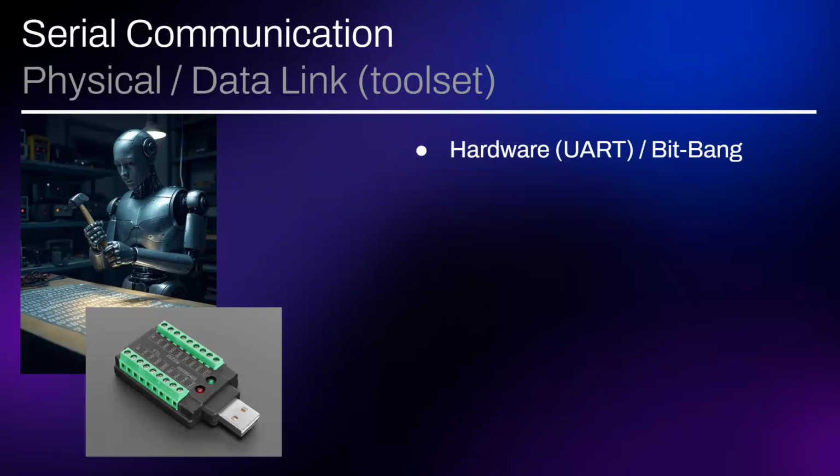And the other option is bit banging, where you have to sit and watch that wire wiggle up and down. You've got to figure out what clock you're in, where you're at in this. You've got to sample it basically multiple times per bit to figure out what's going on there and reassemble that in memory. And it's kind of a pain. Sometimes you have to do it. Sometimes the hardware guys screw up on their hardware, and you have to write some bit bang code to just send it out. I've had situations like that.